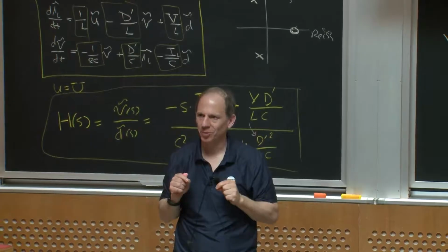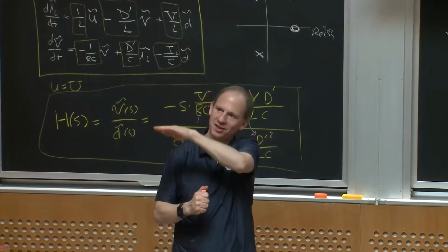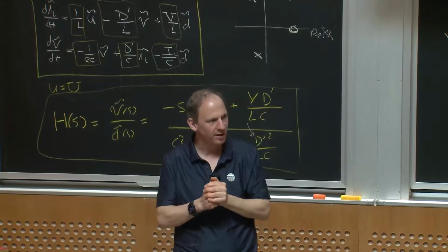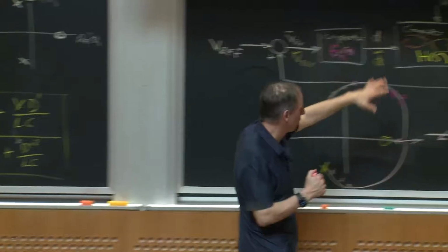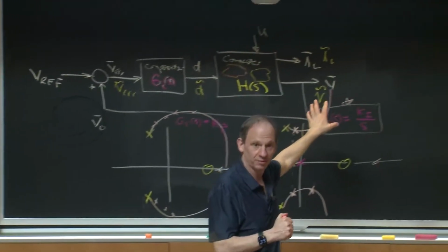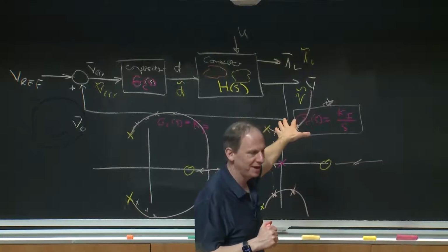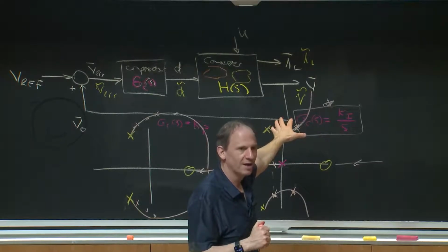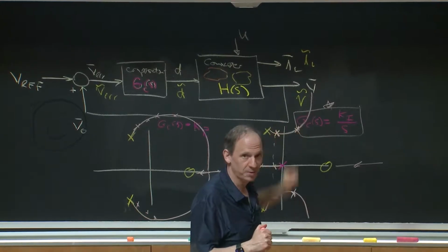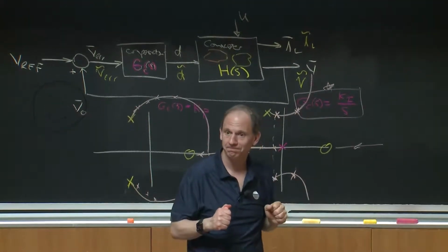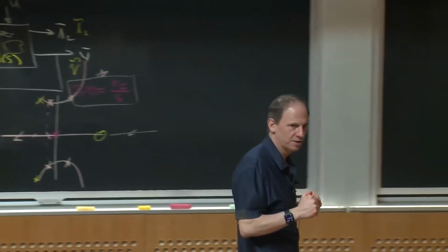And is that acceptable? And in power supplies, very often, your job is to make the world clean, solid voltage no matter what. And in those cases, you've got to think very carefully about how you want to deal with the closed loop poles, right? Maybe you want to make sure that no poles are super lightly damped, even if they're pretty far down and not contributing that much to stability. Maybe they'll make your output response unpleasant. So, that was me talking a lot. Are there any questions about those examples?